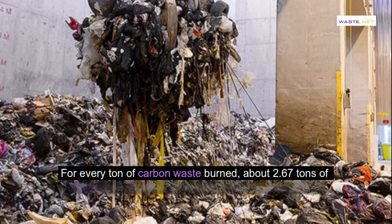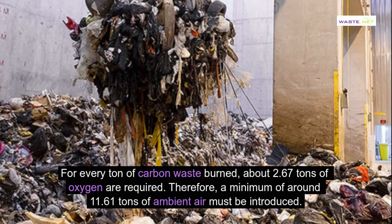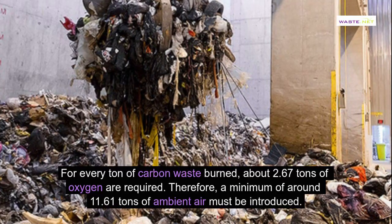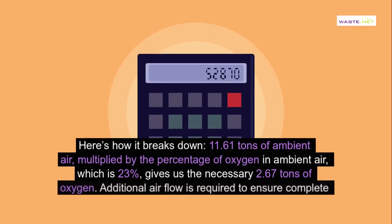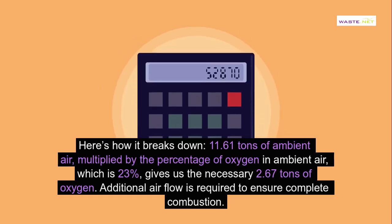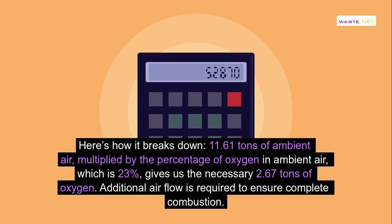For every ton of carbon waste burned, about 2.67 tons of oxygen are required. Therefore, a minimum of around 11.61 tons of ambient air must be introduced. Here's how it breaks down. 11.61 tons of ambient air, multiplied by the percentage of oxygen in ambient air, which is 23%, gives us the necessary 2.67 tons of oxygen. Additional air flow is required to ensure complete combustion.